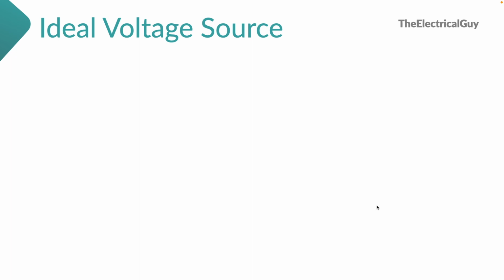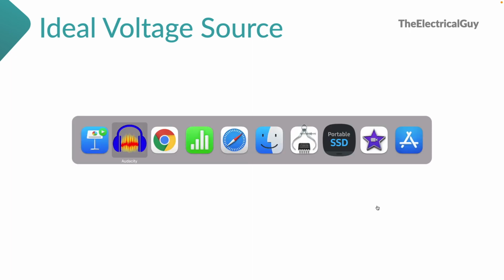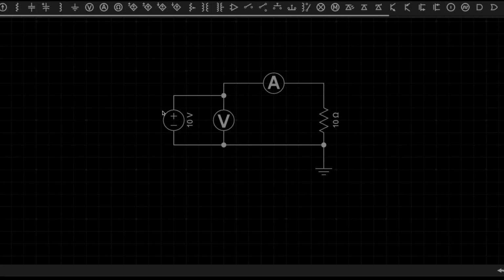Now let's start with the ideal voltage source. To understand what an ideal voltage source is, let's do one simulation. So here we have a simple circuit. In this circuit we have a 10 volt voltage source and a resistor as a load, which is 10 ohms. We have connected a voltmeter across this voltage source to measure the terminal voltage, and we have also connected an ammeter in series to check the current flowing in the circuit.